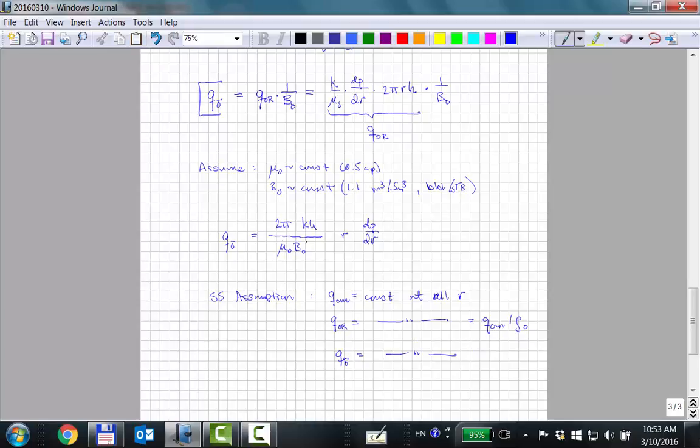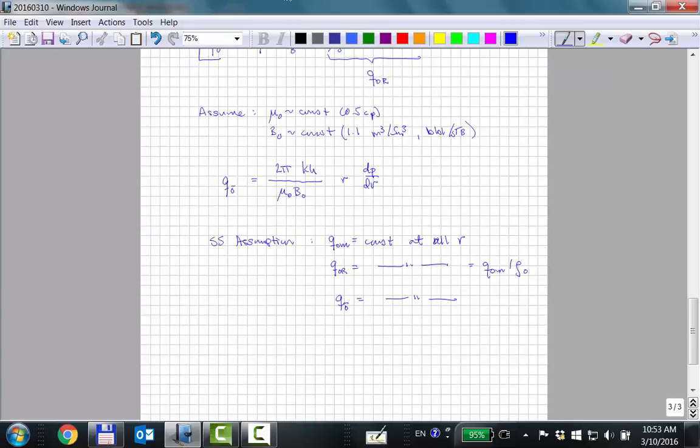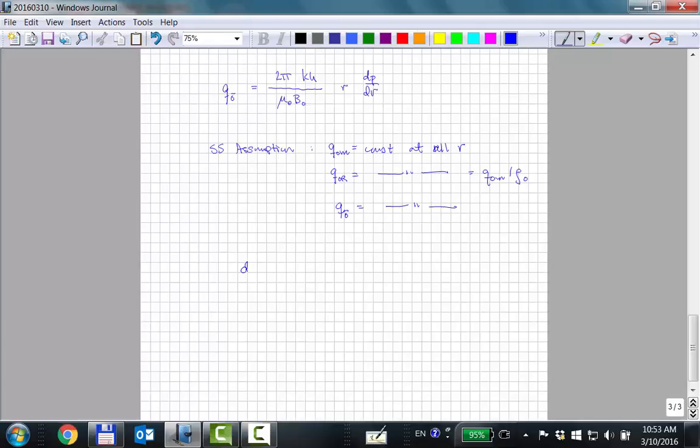So we've got this equation up here, and the QO, stock tank barrels per day, is independent of radius. Because if it was dependent on the radius, then we would have to include it inside the radial integral, the integral on the left-hand side, which we haven't done anything yet. So basically, we're going to bring everything with radius to the left side. You've got 1 over r dr. We've got the QO here, but that's a constant. So when we integrate this, we can take it on the outside because steady state assumptions have been made. This is what steady state assumption means.